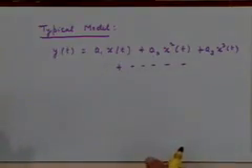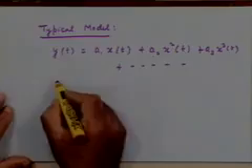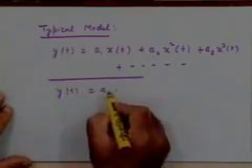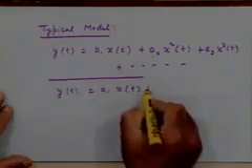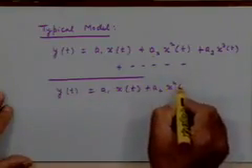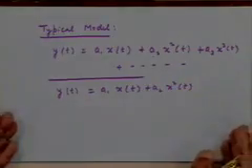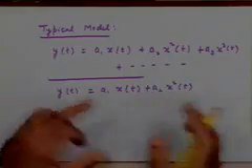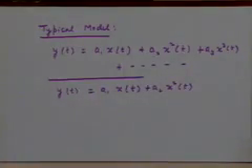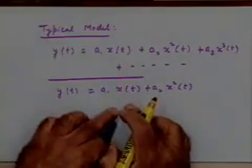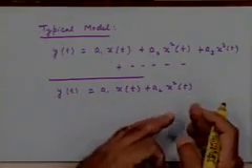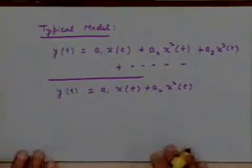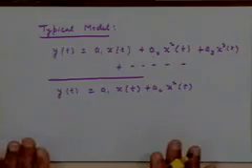Now suppose that is the case. Let's take a very simple nonlinearity of the kind a1 x(t) plus a2 x squared(t). One thing is clear, that the output is not a replica of x(t), and therefore there is a distortion, because we would like the output to be simply proportional to x(t), but we have additional components like x squared, x cubed, and so on and so forth. So therefore there is a kind of distortion here.